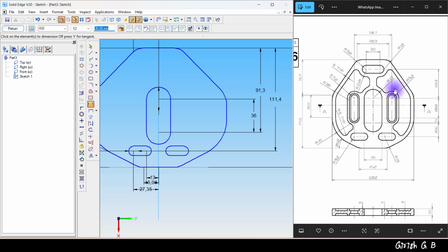We have given the radius as 5.2. Here it is 7.2, which is the outer circle. So the inside circle is radius 5.2. Take a circle, make the radius 5.2, then construct the circle like this, one straight, another one. Then use the equal command. I'm going to equal these two circles.